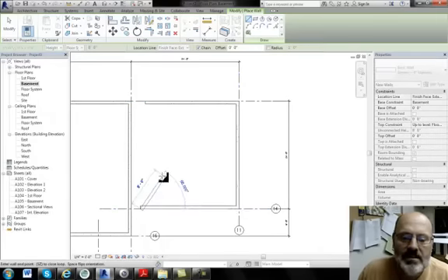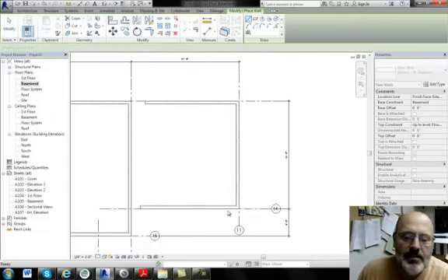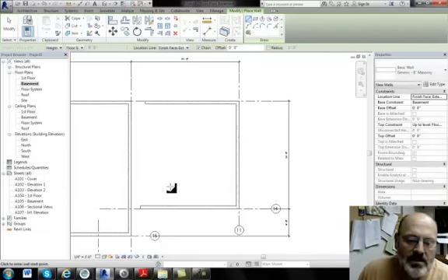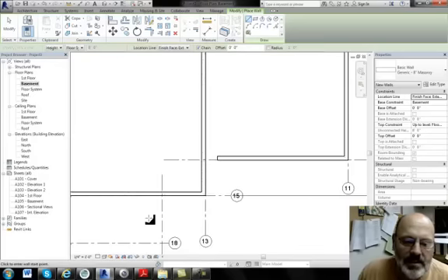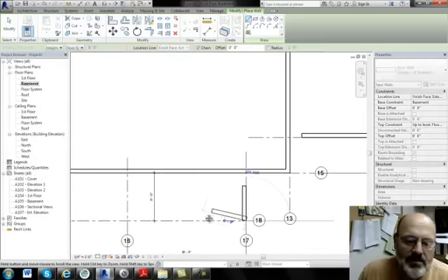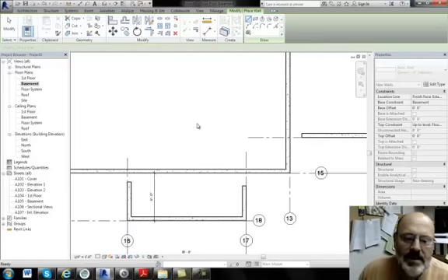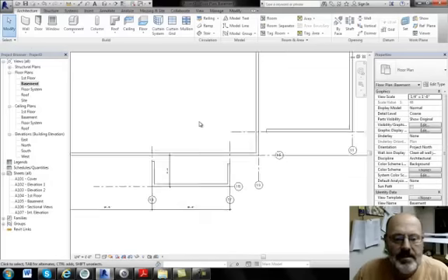I'll fix that later. If I pull this wall into this wall, when I go to change the length of this back wall to 4 feet, it'll change the back basement wall 4 feet. So I always come in and leave a little bit of a space here until I get my walls edited. I just leave a little bit of a gap there, and I can make them close up.